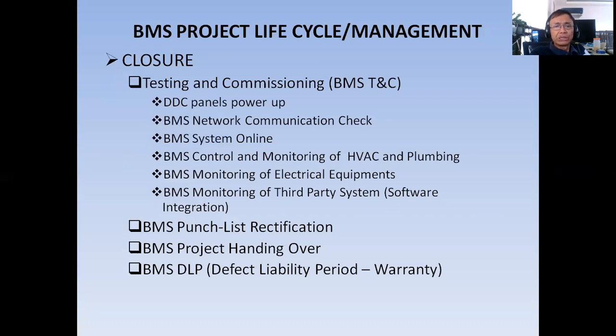Okay. Now testing and commissioning. In testing and commissioning, what you will do is DDC panel power up. Make sure your network communication is not yet terminated on each DDC panel, to avoid some problem. This is the first time you will power up all your DDC panels. One by one, you have to check for the correctness of power supply provision in your DDC panel.